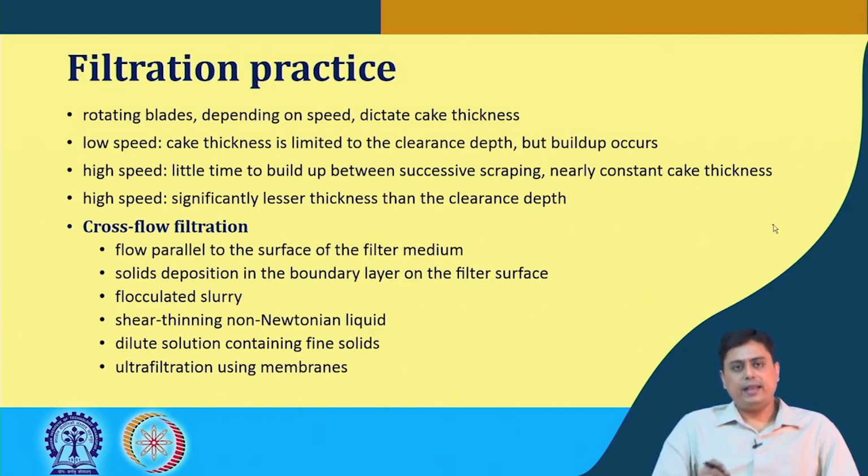But in the case of high speed, there is very little time for this build-up to happen. It continuously removes the excess cake thickness beyond the distance between the filter media and the blade.